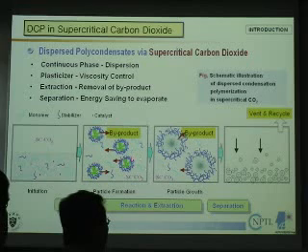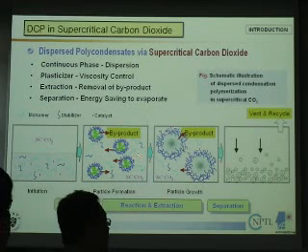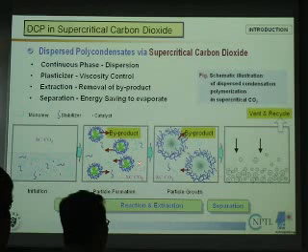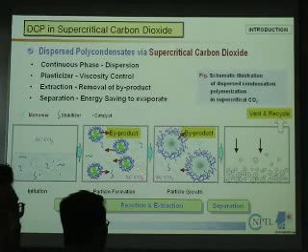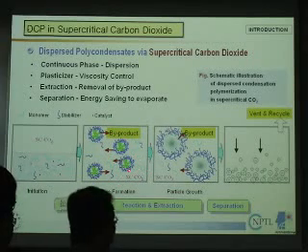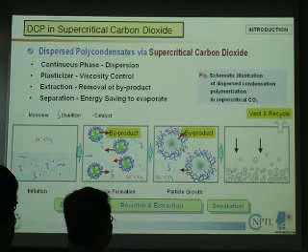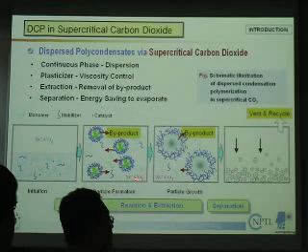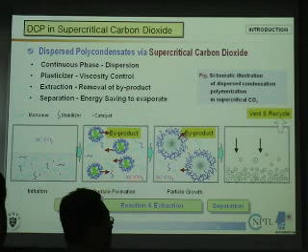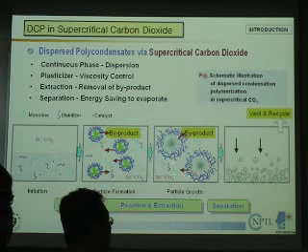That means since you can adjust the solubility power of this supercritical CO2 with the other solvent or other materials generated inside of this particle, you can create the heterogeneous phase of this dispersion in the initial stage, and then you simply adjust the temperature and pressure of this continuous medium. Now you turn into this kind of mode.